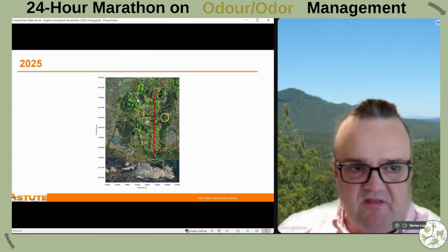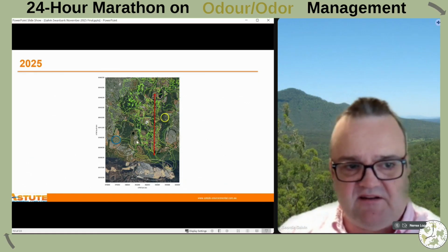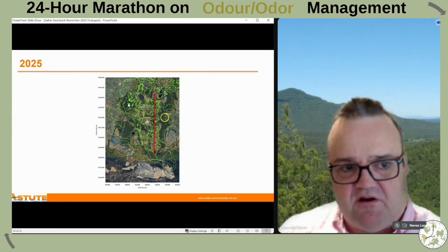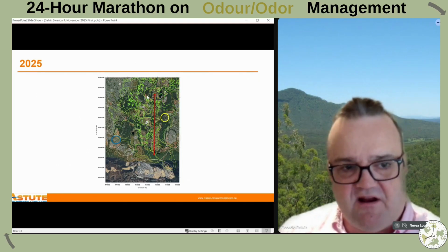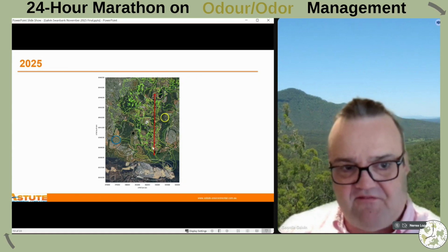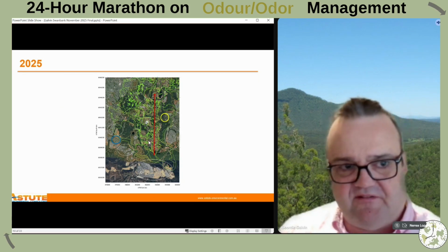But the green lines here, I put them in because anything within those green lines is undercut, which means coal mines have been underneath. The circles are vents from old coal mines, old ventilation shafts, and the arrows, which may be hard to see, they're drives, so they show where the underground mines have gone and cut in under the ground. So you can see, in terms of land use planning, it does make sense to make use of that area for industrial purposes as opposed to residential.